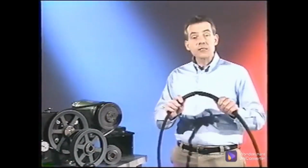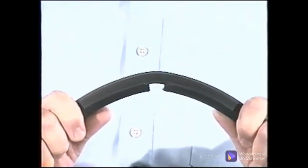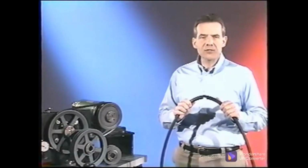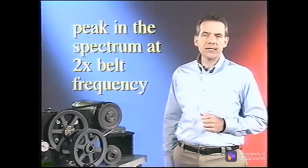Defects on belts can be cracks, splits, or like this, may have chunks missing from the belt. Any of these defects on a belt bump the sheave as it rolls onto it, generating a pulse that can be measured with a vibration sensor. Since the defect bumps both sheaves during one circuit of the belt, there is a peak in the spectral data equal to 2 times the belt rotational frequency.